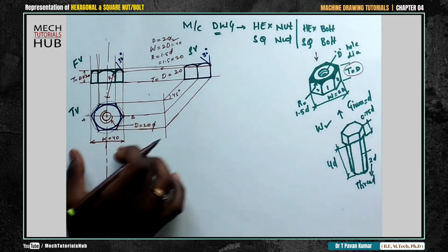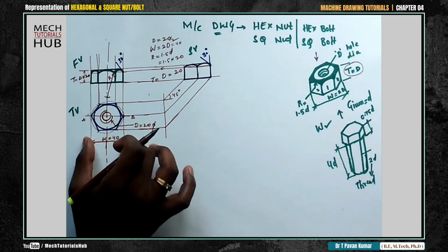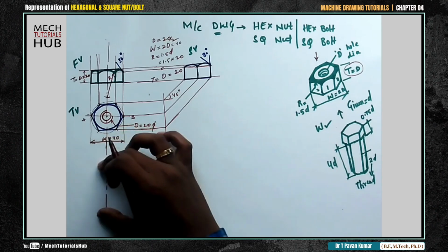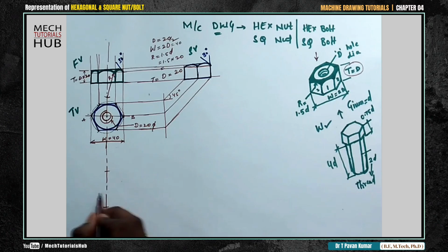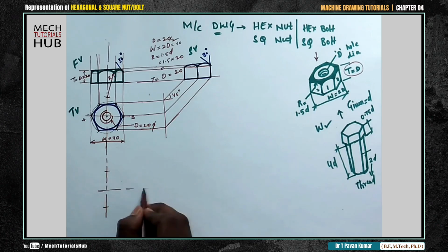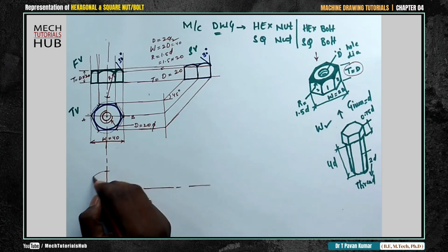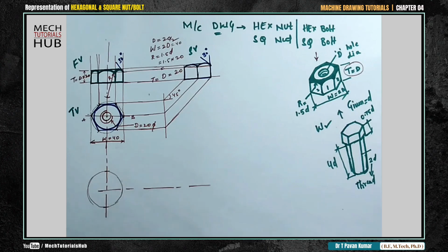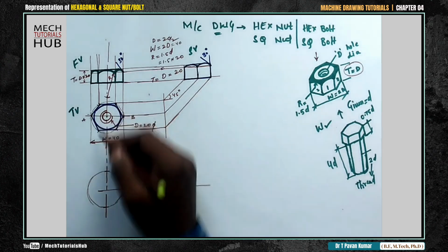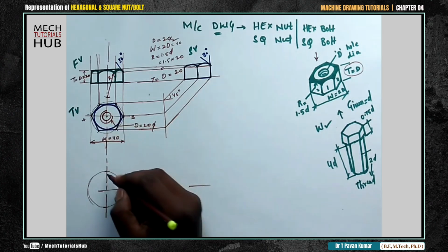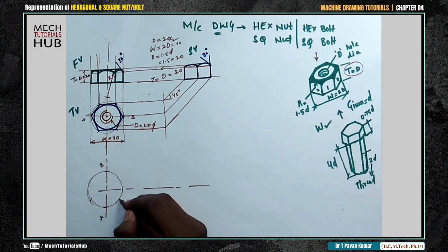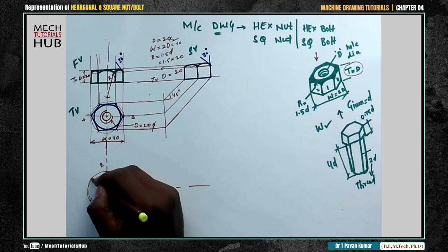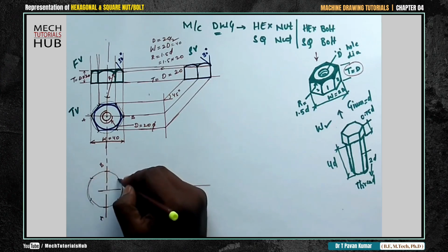Initially for a nut we considered this as the width. Now rotate your width, consider this as your width. I'll make a mark of W and centrally place an axis line. Then again draw a circle with a 2H pencil. Then as before, take this as the radius and this as the center; call this A and this B. With A as center, make a mark above and below. With B as center and D as radius, make a mark above and below.